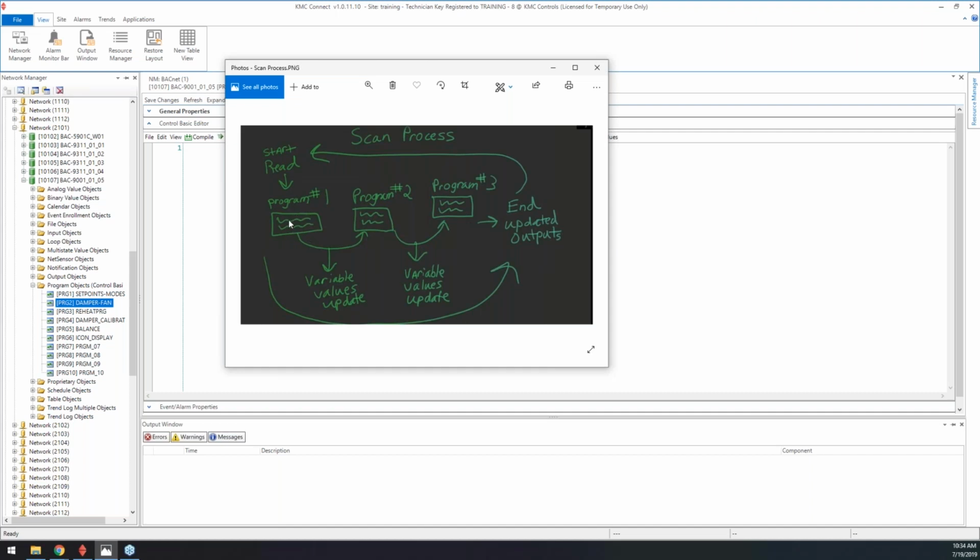We're determining if we're going to be in heating or cooling. We're going to be determining maybe set point limits and things like that, setting ourselves up for more of the control functions in subsequent programs. But as this program runs, anytime we're starting or stopping a variable, we're going to update that variable in real time, so that way we can use it in the same program or in subsequent programs. If we're starting and stopping an output, we're going to hold that value until the end of the scan before it's updated. And we'll talk about why that's important here in a second.